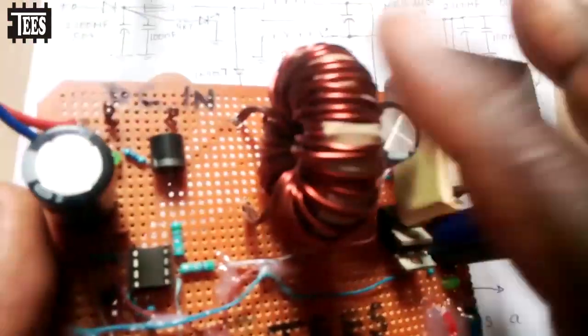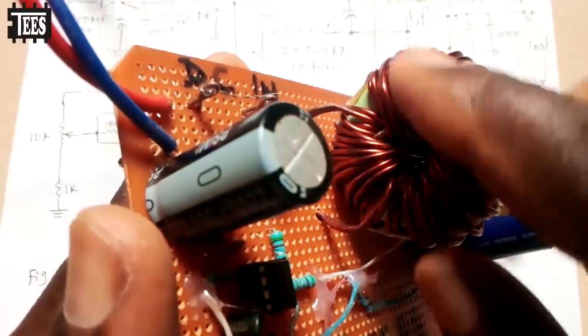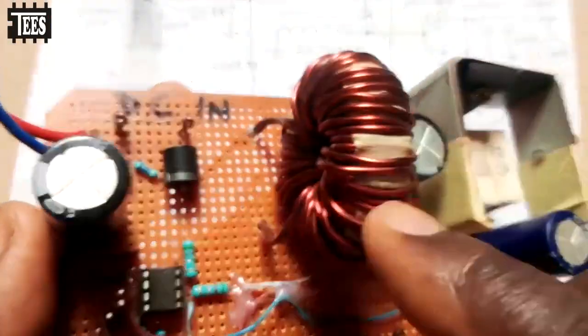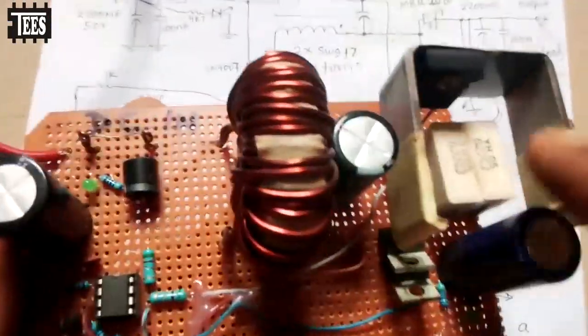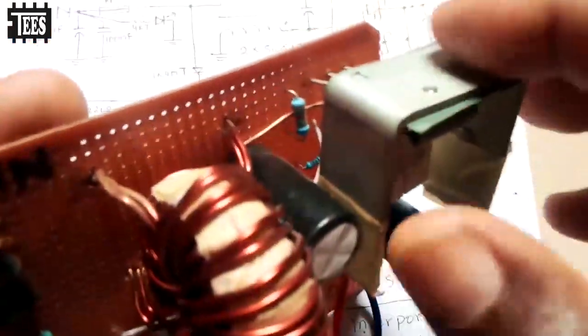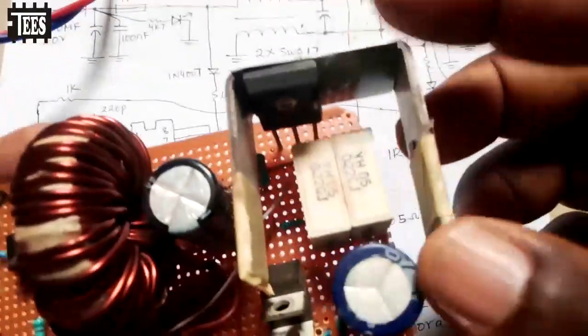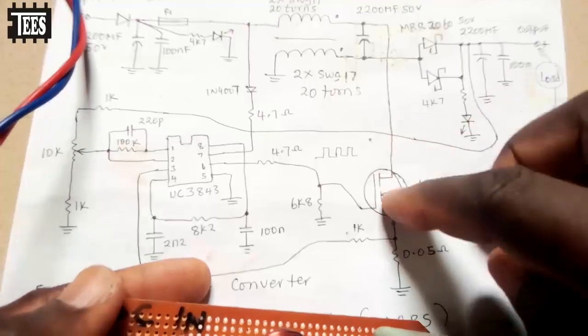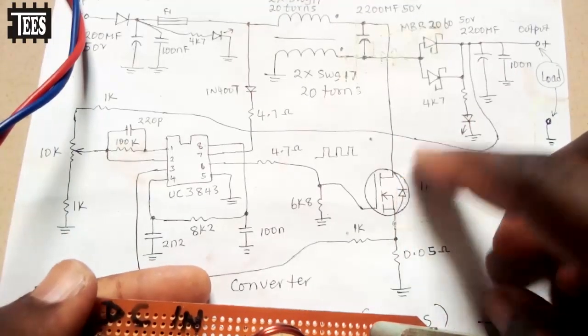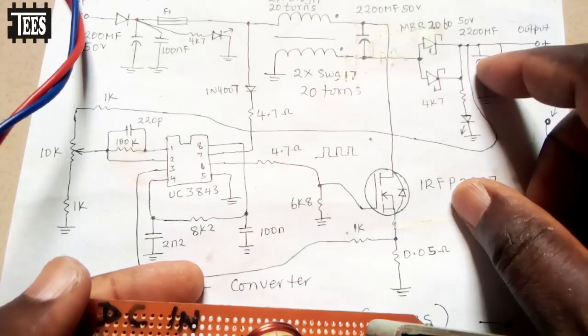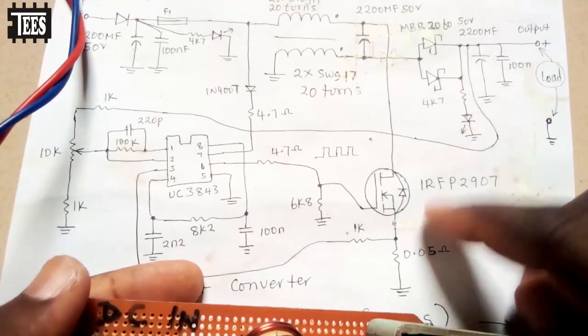So it's all like this one there. I bought the coil, but the ring, I removed it from some old circuit boards. And also this, if you open your laptop charger, you'll be seeing this. So I removed this from an old spoiled laptop charger. So I have to attach this to a heat sink. When you are putting this thing, it is very necessary, because this gets hot when you've powered it, when you connect a load here. The more current the load is drawing, the hotter it gets.